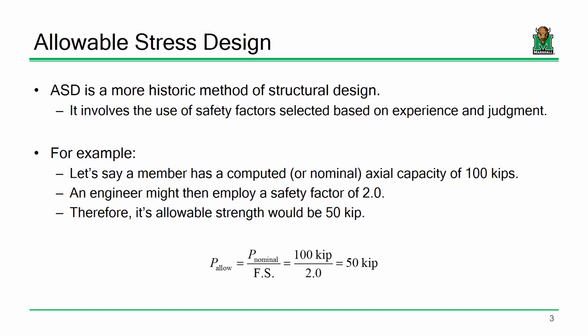Okay, so allowable stress is a pretty basic concept. I go down to the lab and I take this table with me and I put it under an actuator because I like breaking things. My general philosophy is any day with controlled demolition is a good day. So I put it under an actuator and I start pressing down on this thing until, boom, it breaks, okay? And let's say I do the math and I find that this table breaks at 800 pounds. So I know that this table will physically fail at a load of 800 pounds.